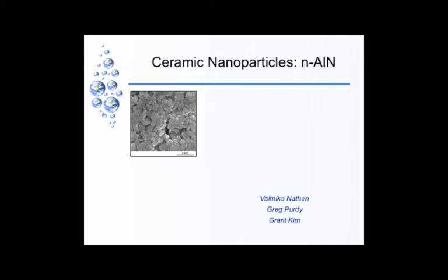Okay. We talked about aluminum nitride. Do you remember what are some interesting properties of aluminum nitride? Yes, so it is electrically resistant but thermally conductive, right? So thermal conductivity is high, electrical conductivity is low, and so you would use that for a package, right? Also, the coefficient of thermal expansion is very low and similar to silicon carbide and silicon materials, and so it is useful for packaging applications.